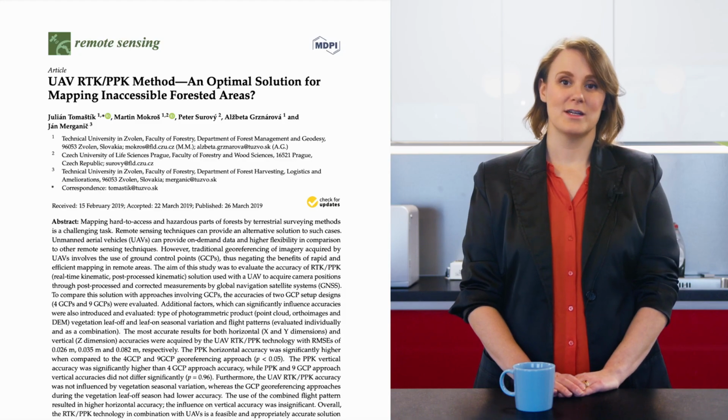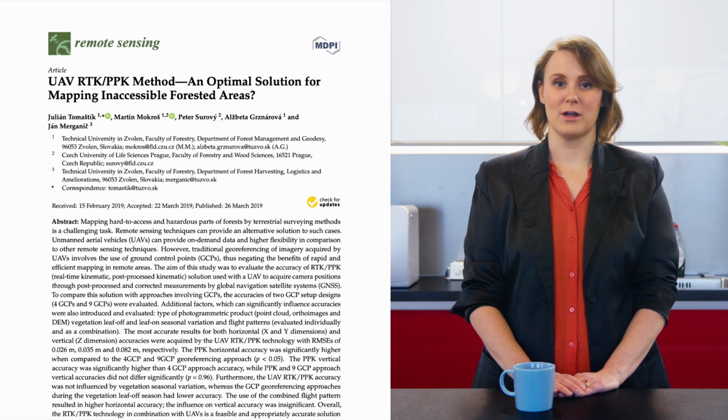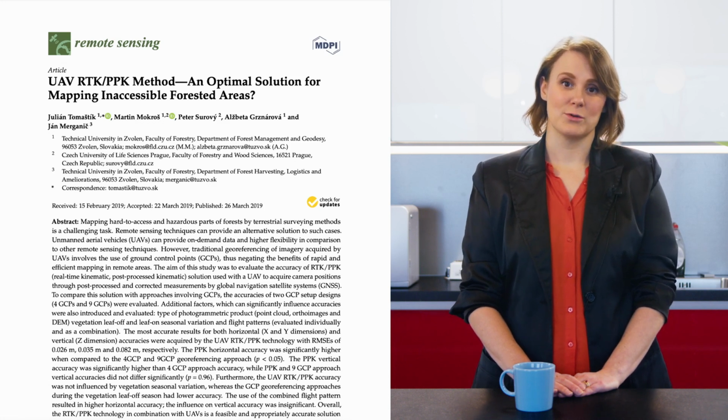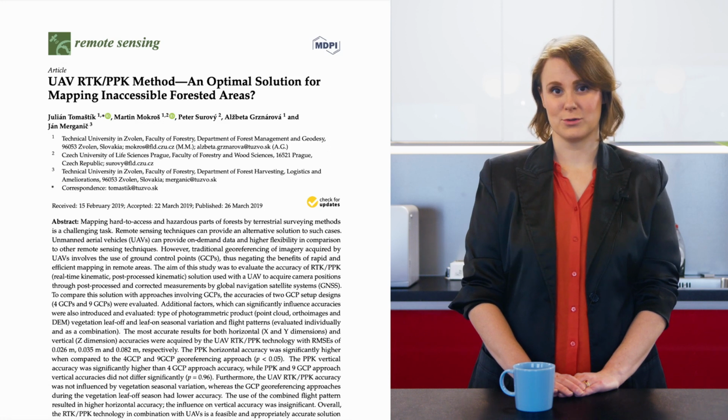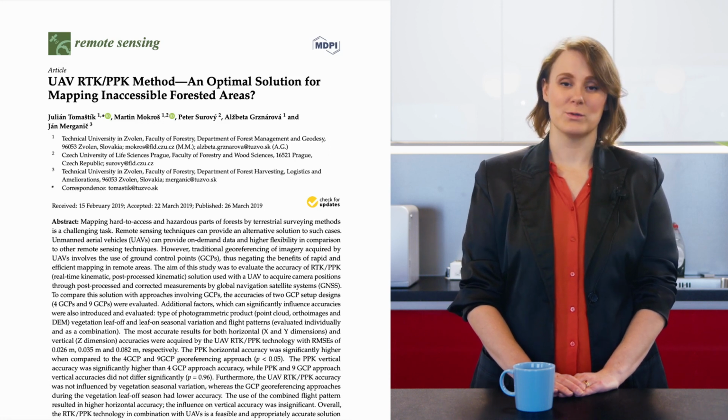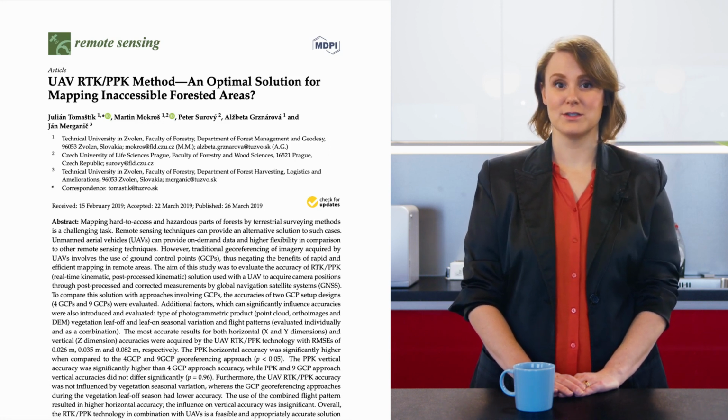A study published in 2019 in Remote Sensing showed that in rural areas with a lot of forest, the RTK drone performed better than the traditional drone using ground control points and was more consistent with seasonal changes in vegetation. This is a good note to remember for construction sites that are operating over several months or even years. The changes on a construction site are significant, and therefore the RTK drone provides a more consistent precision of data.